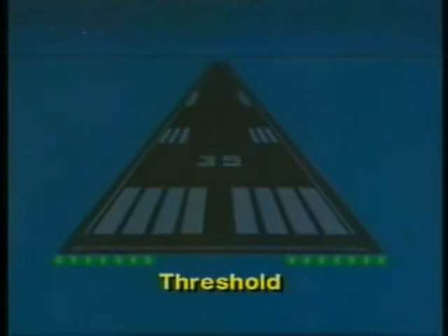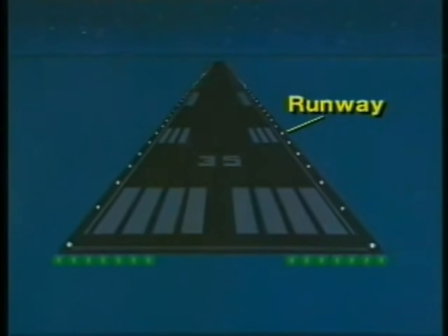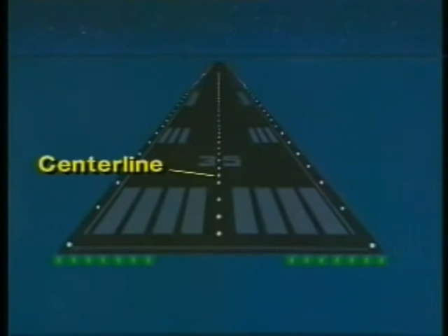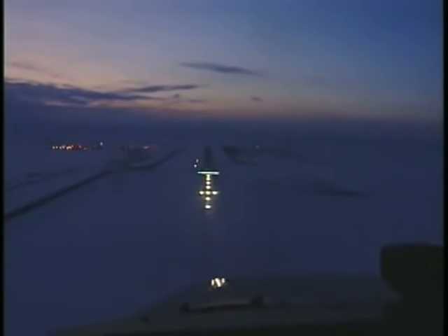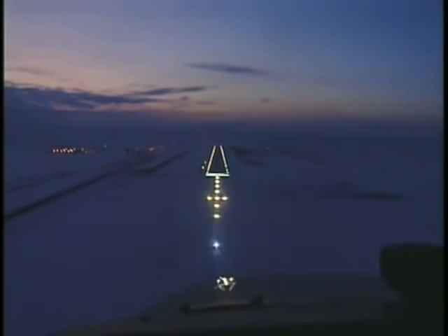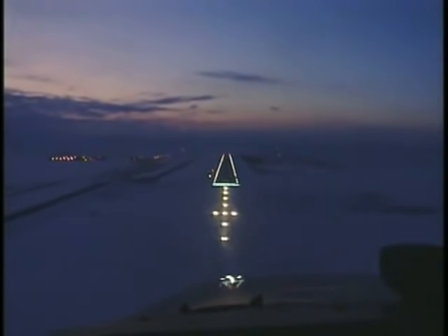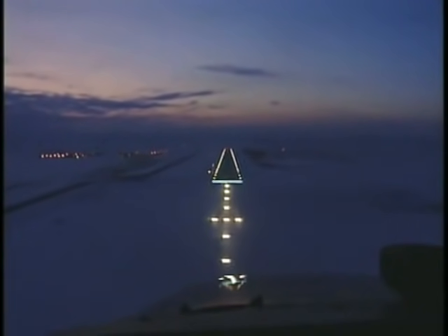The lighting on the runway itself also helps you identify the runway environment and maintain your orientation during the final approach. At some airports, you control the airport lights as well as their intensity by keying the microphone a specific number of times within a certain time period. It's important to check the AIM for proper procedures to activate the various lighting systems. At most monitored airports or ones with a full-time control tower, you can request the tower or flight service station to temporarily adjust the lights for you.